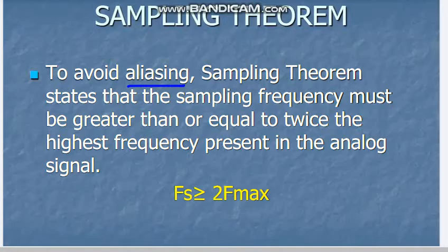That means we take the maximum operating frequency, double it, and that, being greater than or equal, should be the sampling frequency.